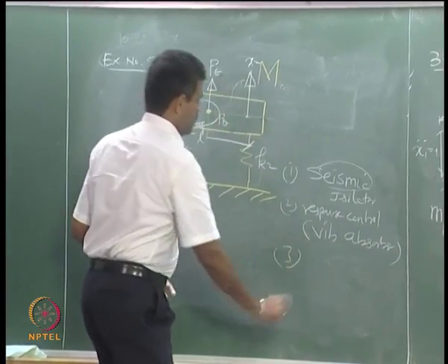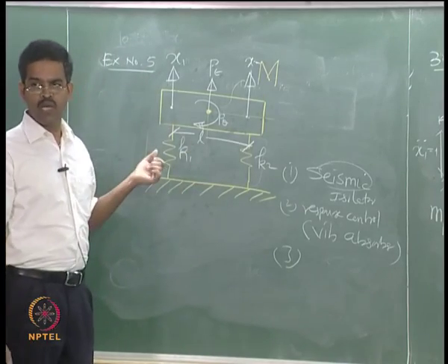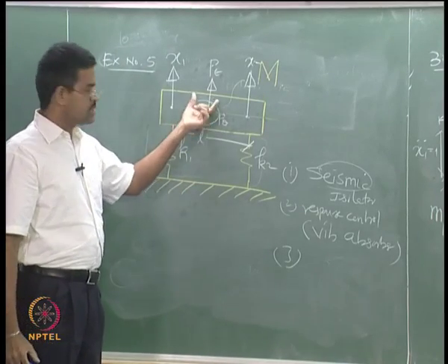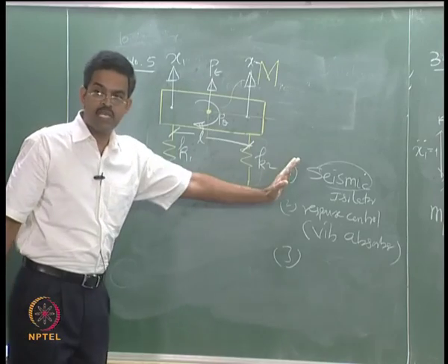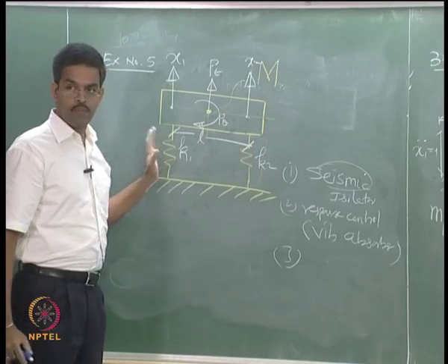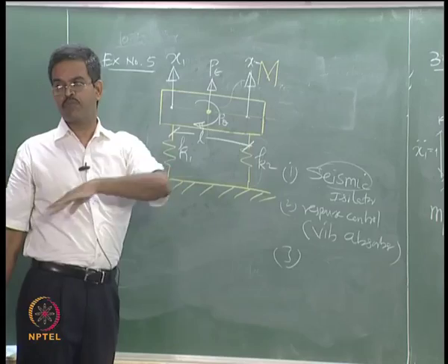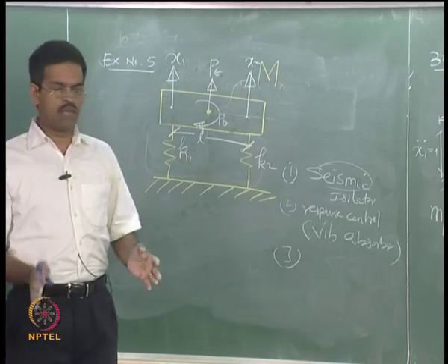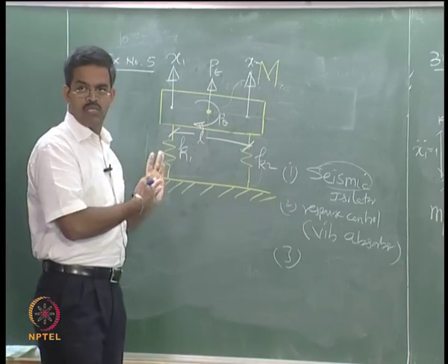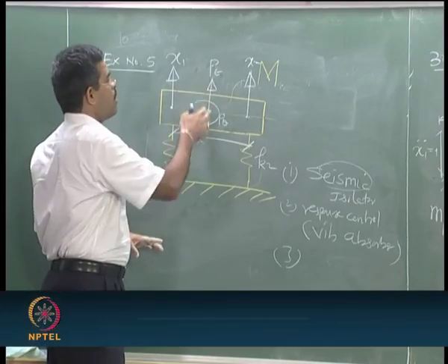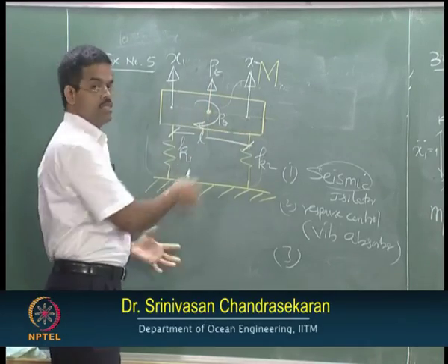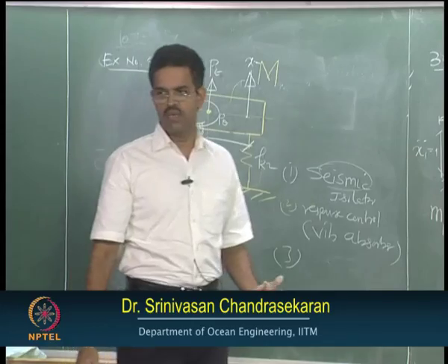The third is an interesting geotechnical model where the superstructure is resting on the foundation on Winkler springs, where Winkler springs are represented as an equivalent series of springs like this. So there are many practical applications of the line diagram you see here, where the forces are all applied to the mass center, but the displacements need not be at the mass center.